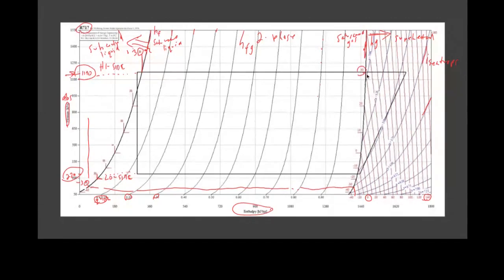You can see it again, and then it shoots down to here. Okay, so there's plus 30 degrees Celsius on that line of constant temperature. So it's kind of a zigzaggy line. So at 1190, the saturation temperature is 30 degrees Celsius, ish.